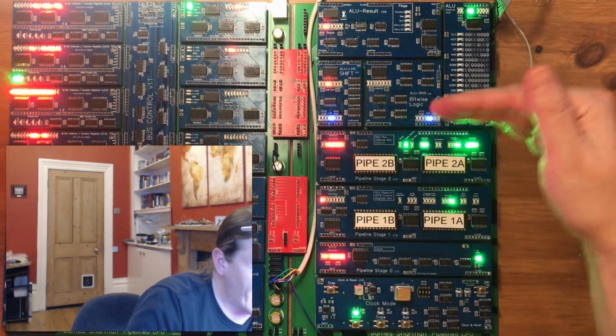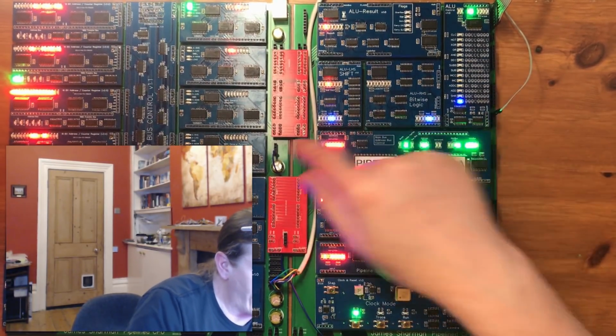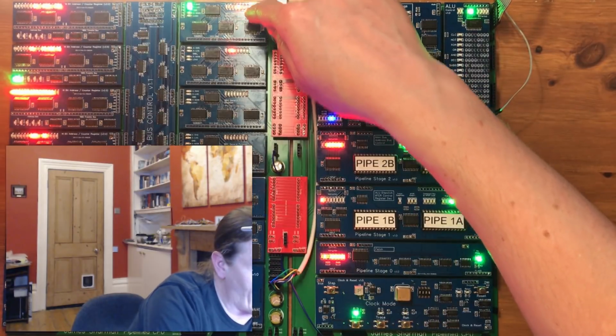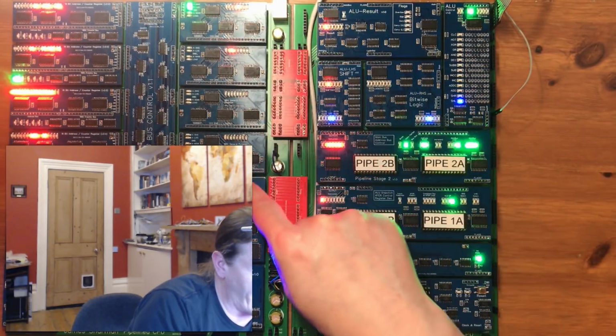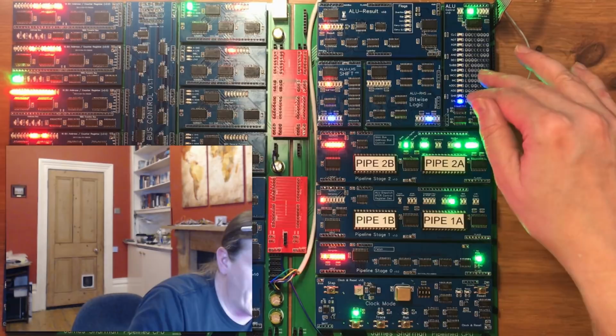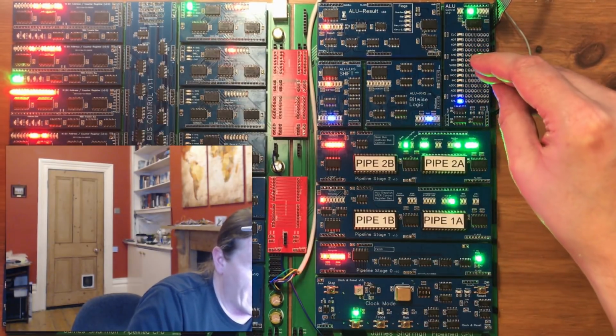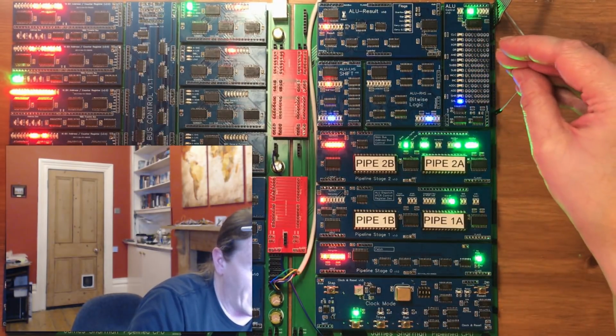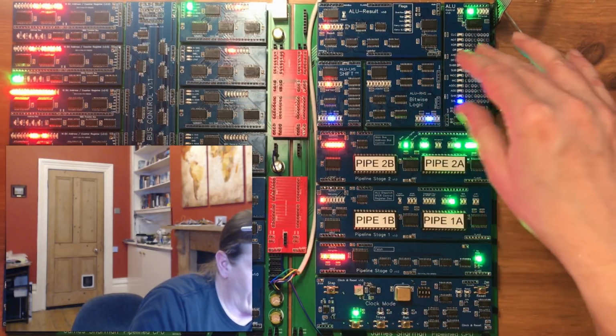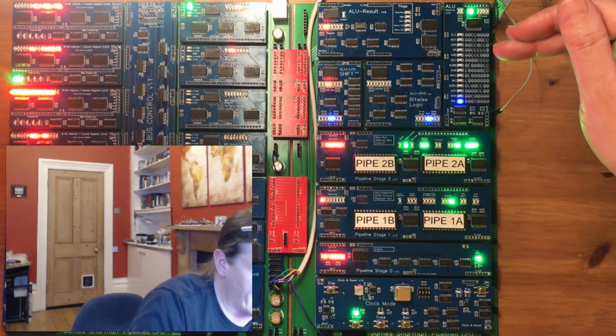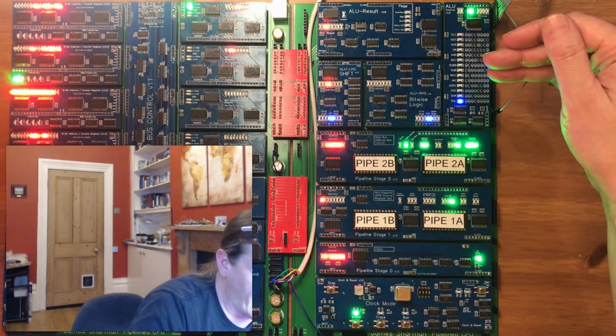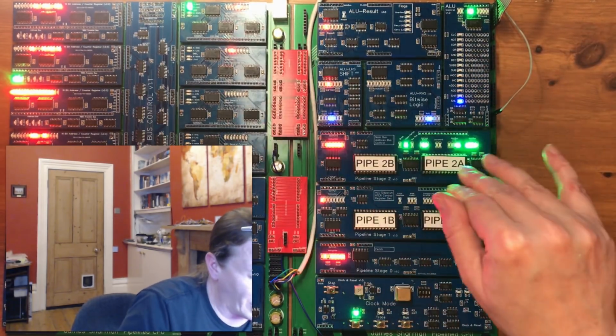And so I could have actually used that model, and that would have saved me one chip from each of the general purpose registers. Now, I would have needed to make sure I've got a preserving operation in the ALU, but I've got at least one state flag that I haven't used, so I reckon I could have probably done that.